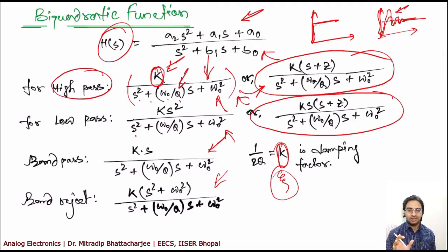Okay, we will use 2 sections, but if we get a very good filter using those 2 sections, then why should we go for higher? Because anyway, if I put a high number of sections, then it will take space in the silicon chip, and in the silicon chip it's really very costly, right? Each micron matters. As I said, you need a very small chip. That's why the cost issue comes into the picture.